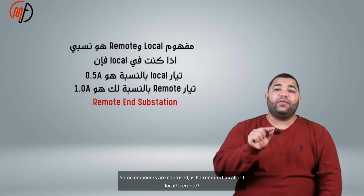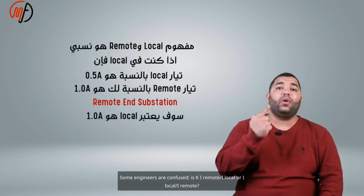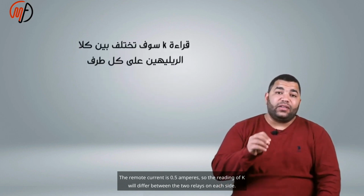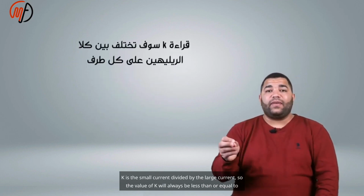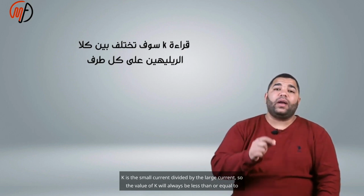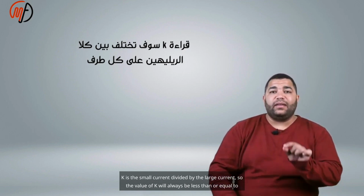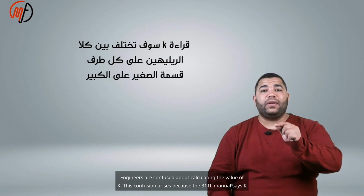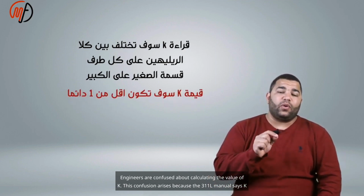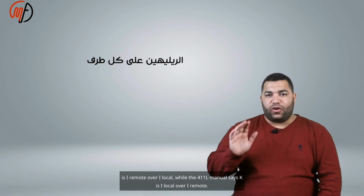Some engineers are confused. Is K I remote over I local, or I local over I remote? The remote current is 0.5 amperes, so the reading of K will differ between the two relays on each side. K is the small current divided by the large current, so the value of K will always be less than or equal to 1. Engineers are confused about calculating the value of K. This confusion arises because the 311L manual says K is I remote over I local, while the 411L manual says K is I local over I remote.